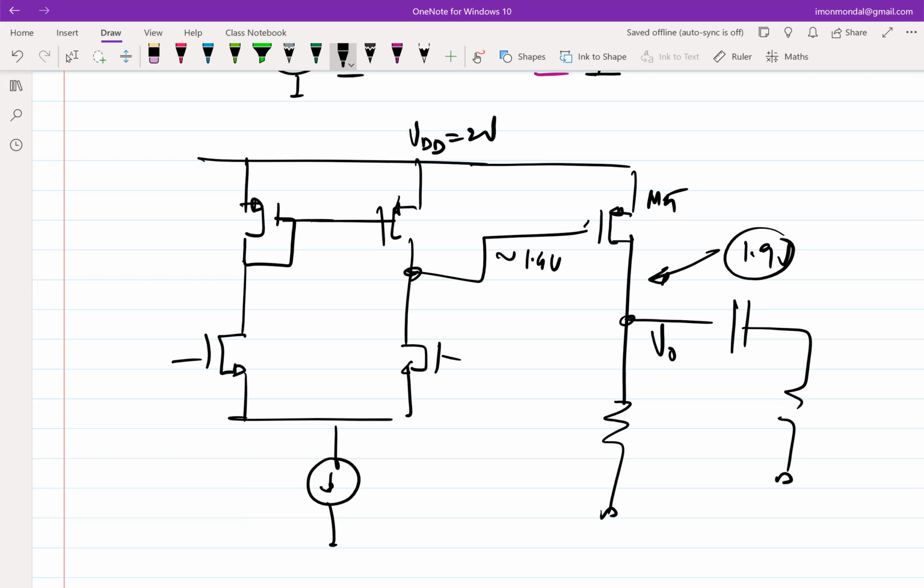So you mean that current will go to this, that M5 current will go zero if we will not. No, that depends on the quiescent stage, right? I'm saying that if the output signal swings, the incremental current can go through the resistance, right? If the output swings and this voltage is going low, which means that you are dragging less current, which means there is an incremental current flowing in that direction, right? So we are trying to figure out whether the output has a range to swing. So under this quiescent condition, do you believe the PMOS is the better way, second stage, or NMOS is the better way? PMOS seems to be better, right?